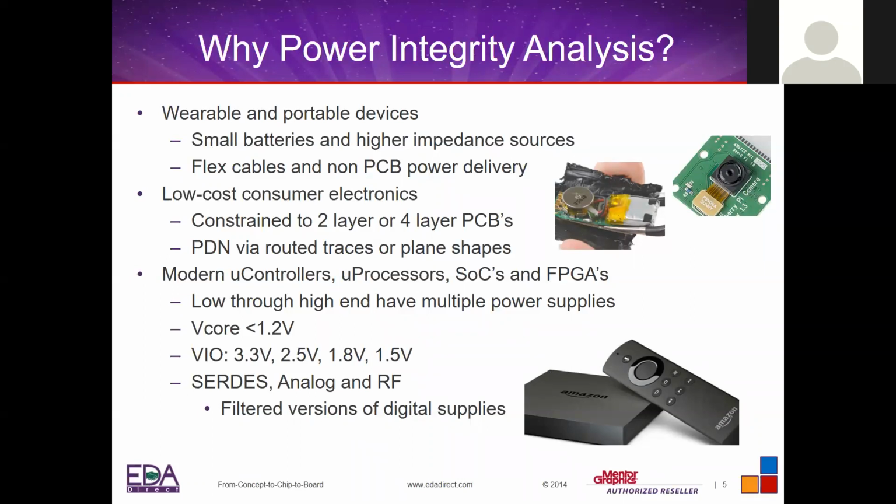And also because of the smaller form factor, you may be constrained to not as many layers in your PCB, and you don't necessarily have a full plane to take advantage of things like EMI shielding and impedance control. So this creates problems in these smaller types of designs.